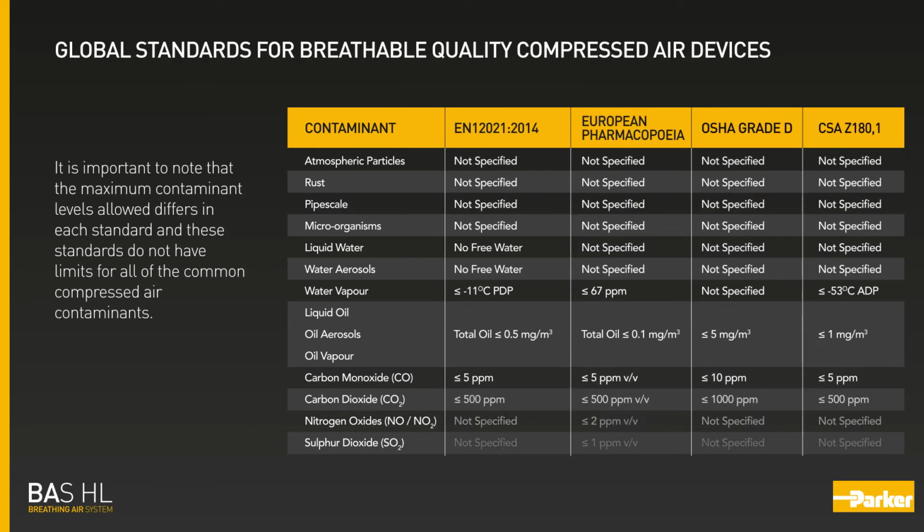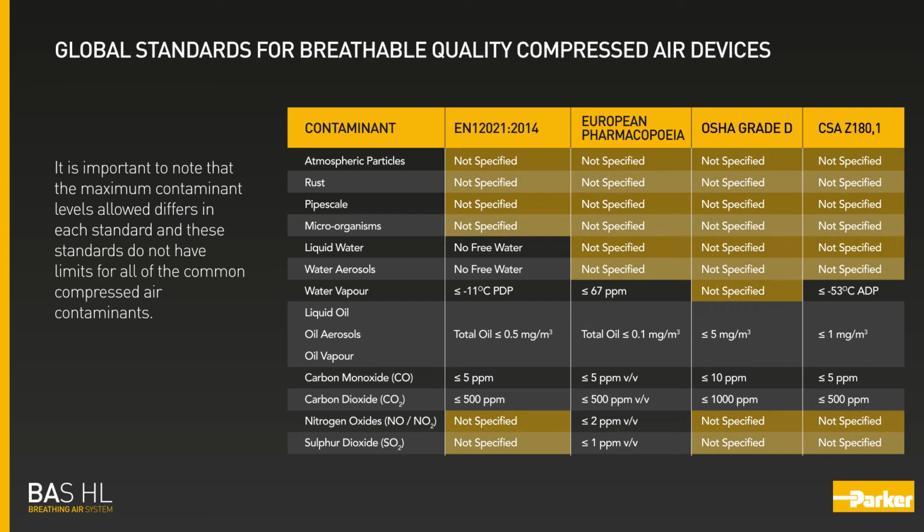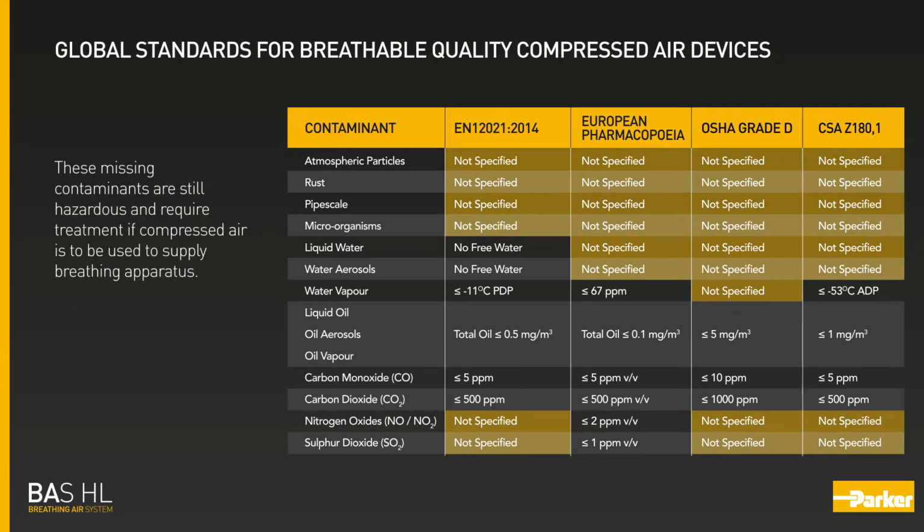It is important to note that the maximum contaminant levels allowed differ in each standard, and these standards do not have limits for all of the common compressed air contaminants. These missing contaminants are still hazardous and require treatment if compressed air is to supply breathing apparatus.